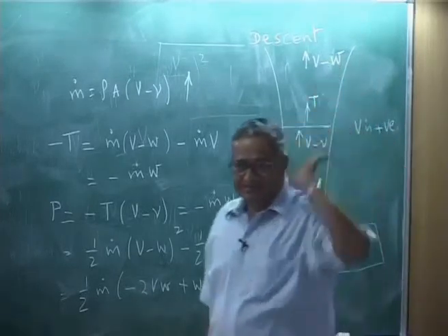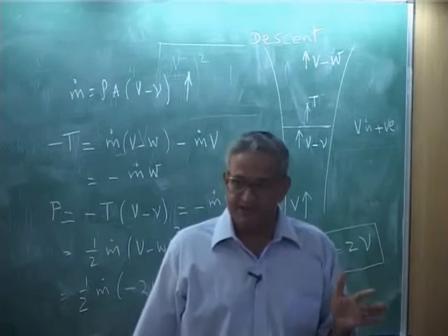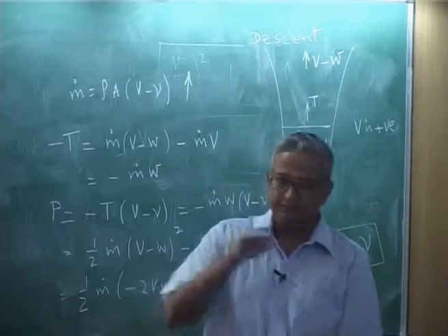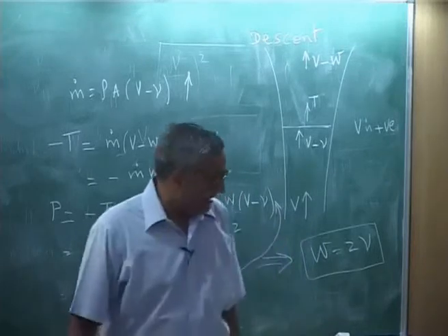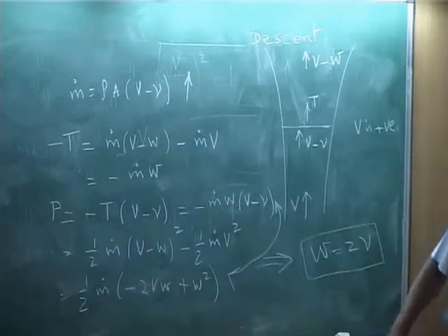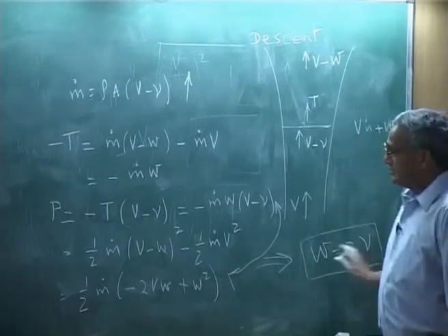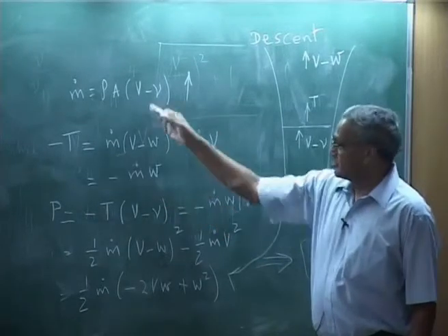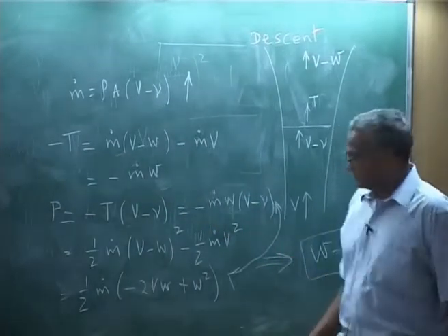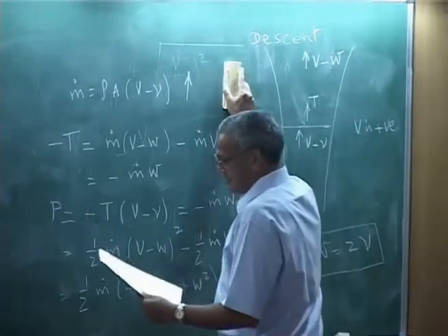The far field induced velocity due to the rotor disc is actually double of what happens at the rotor disc. Okay. Now, you look at your thrust, because you got this expression, my thrust is here. Okay. I will be substituting this quantity here. So, let me put the thrust, I will write here.